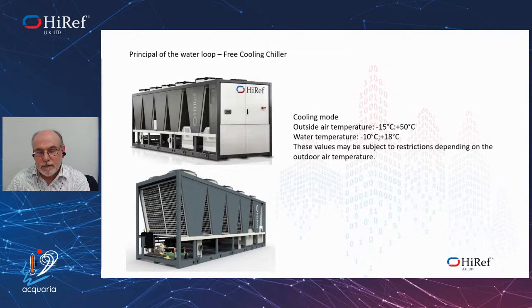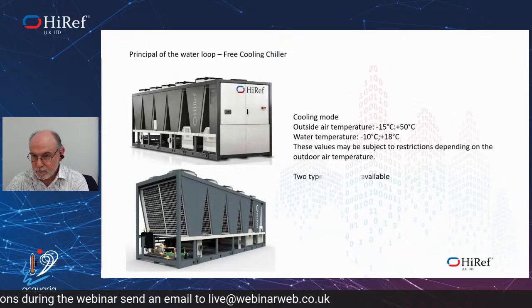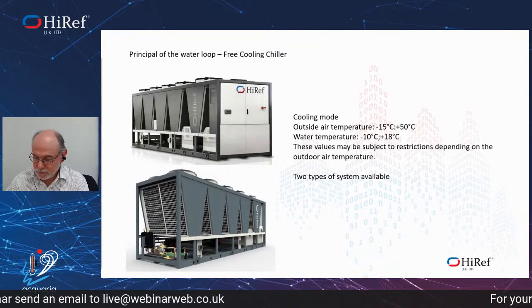So you can look at cooling the water down through the free cooling mode, and then the mechanical cooling coming on to ensure that you're staying within those temperatures. And the higher the water temperature, the more efficient the free cooling system is, and also the chiller itself.